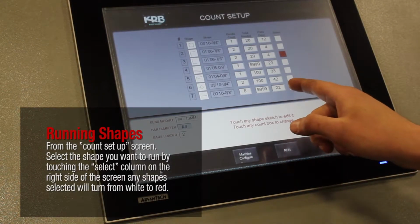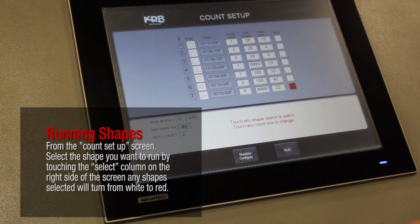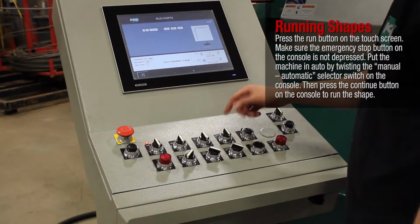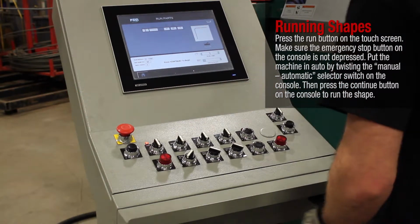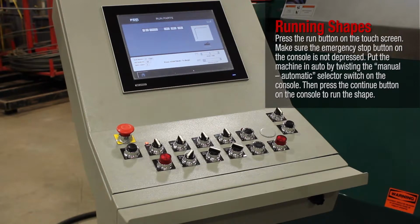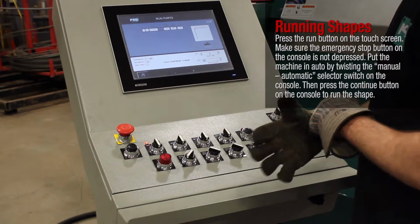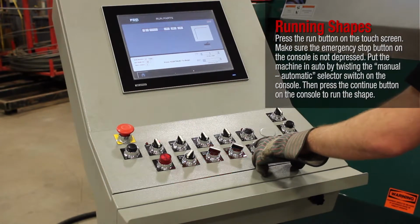Running shapes. From the Count Setup screen, select the shape you want to run by touching the Select column on the right side of the screen. Any shape selected will turn from white to red. Press the Run button on the touchscreen. Make sure the emergency stop button on the console is not depressed. Put the machine in auto by twisting the manual automatic selector switch on the console. Then press the Continue button on the console to run the shape.